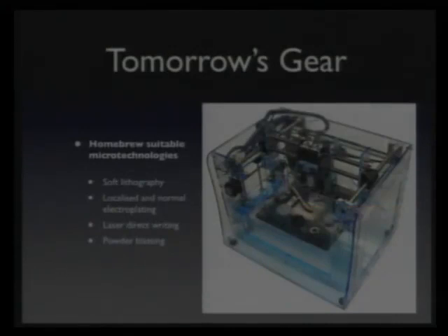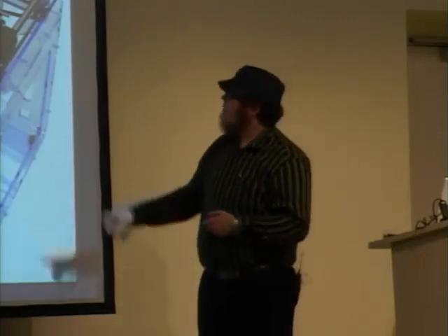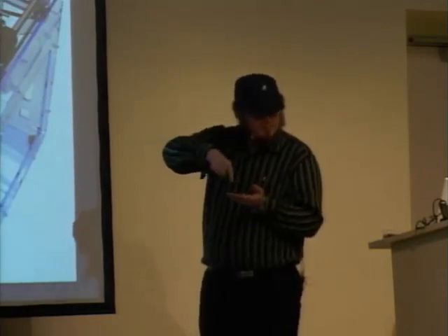This is the other project, the Fab at Home project, which is really nice for future technologies because all the microsystems today are made by photolithography. The mask you use for the initial structuring is done by a photosensitive polymer, and you need a big photo lamp and a mask to do it, or a laser. What this does is print out the polymer just where you need it, so you don't need the photo step.